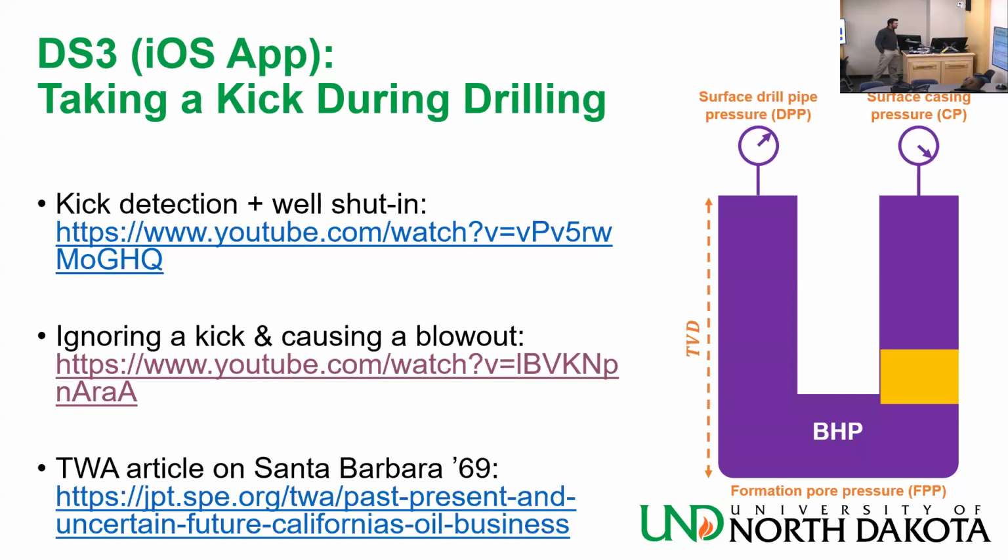But yeah, it becomes bigger and bigger. Also, back to your question, well, it wasn't really your question, but it was whether you can save it when the whole annulus is almost filled with the kick. And I said the answer could be. One thing that plays a role is where your casing shoe is. If your casing shoe is very low, if you had just run casing and cemented it and you did a good cement job and everything was fine, I mean, your vulnerable point is the casing shoe depth, which is basically the reservoir. So you are okay.